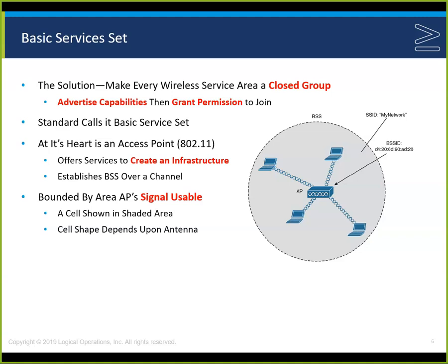Think about these things as when the signal gets on the antenna, there is a certain amount of power that's available to it. In the omni, it goes out in all directions. If we focus it with a directional antenna, we now concentrate that same amount of power in a smaller area. And that's one of the reasons that the directional antennas are going to have a greater distance than the omnidirectional antennas. And the distances that we talk about are all going to be in perfect circumstances too: no impedance, an open field, great atmospherics, no absorption of the signal.